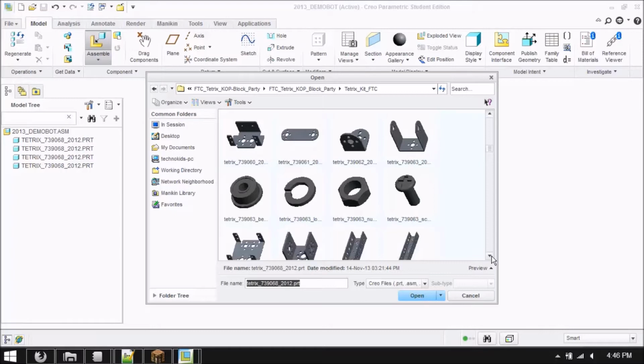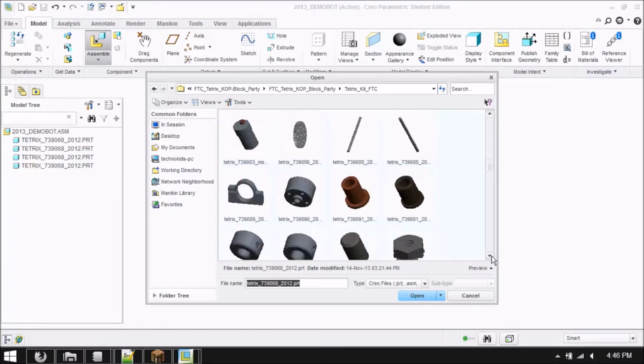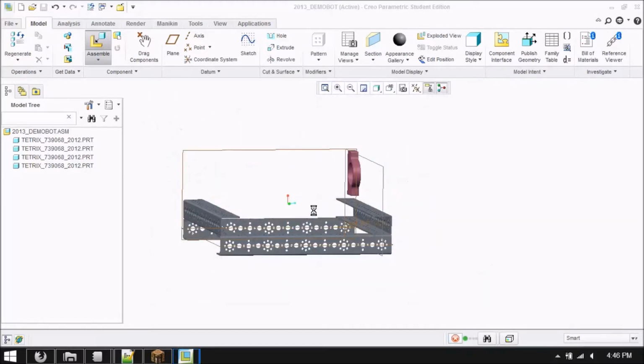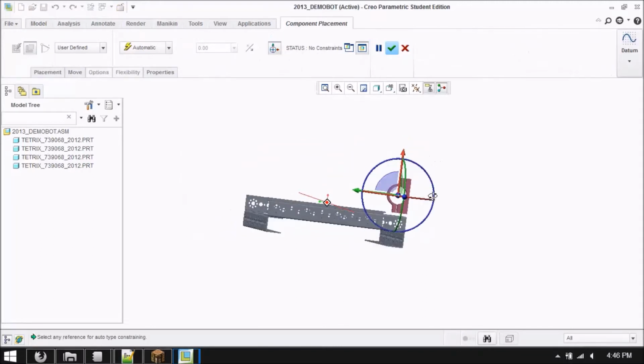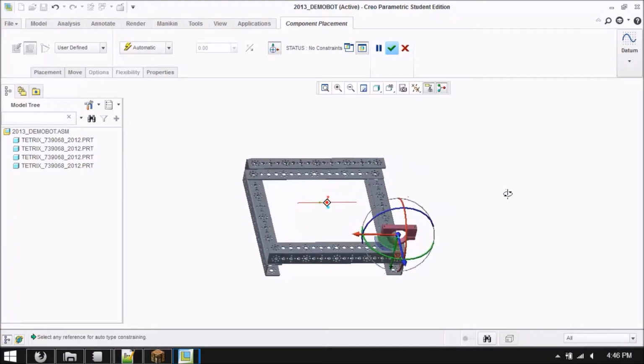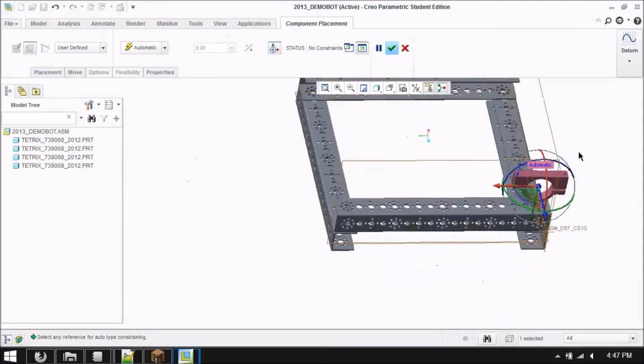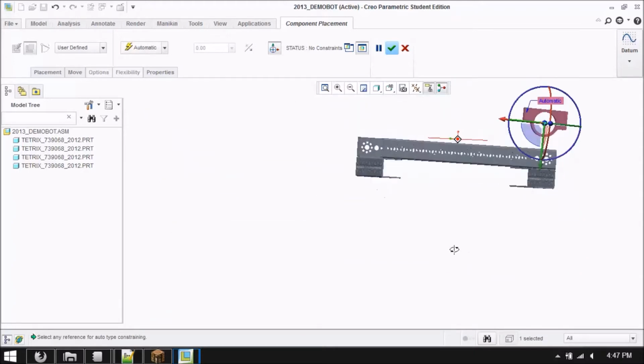First things first though, before I can add a wheel I need to add the motor, and before I can add the motor I need to add the bracket. So that's what I'm going to do first. The process of adding this is really the same as adding any other part. You just select the hole, then select where you want it to be matched up with.